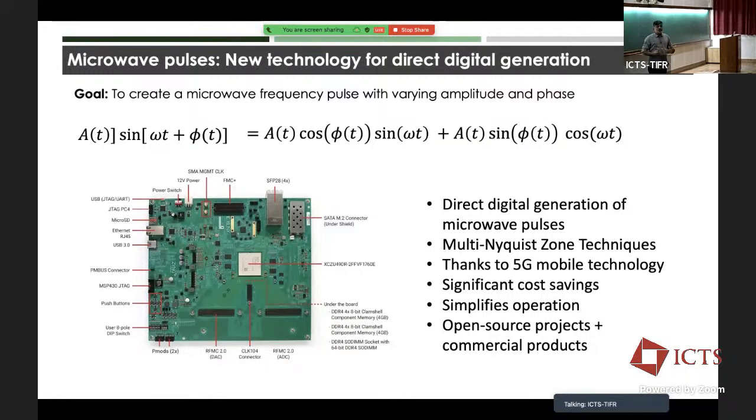But it essentially uses the nonlinearity of these processes to look at images of the signals, and you can create high frequency signals even though your digitizer or your DAC is actually updating very slowly, by choosing appropriate filters. And this has brought down the cost of these DACs very low. And again, the reason is that 5G cell phones use frequencies in exactly the same range.